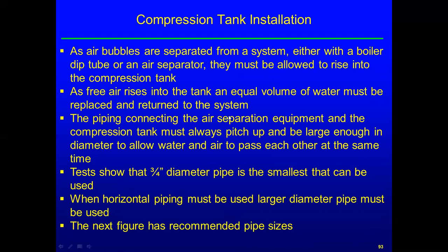The piping connection to the air separation equipment and the compression tank must always pitch up and be large enough in diameter to allow the water and the air to pass each other at the same time. At least a 3/4 inch diameter pipe is needed.